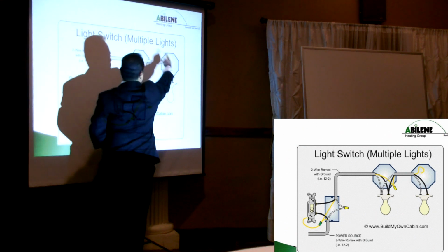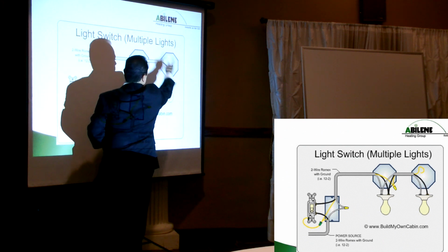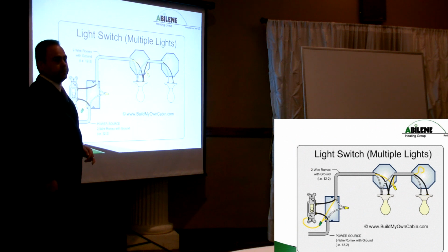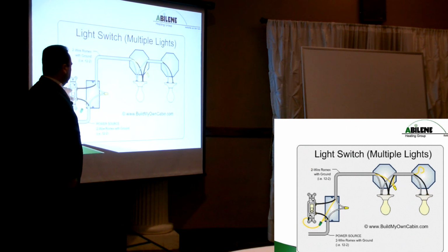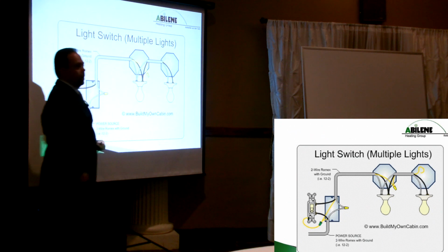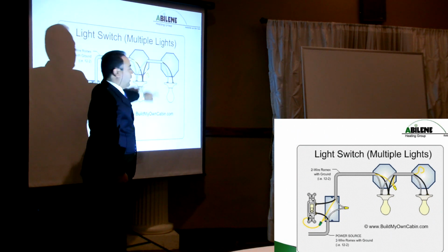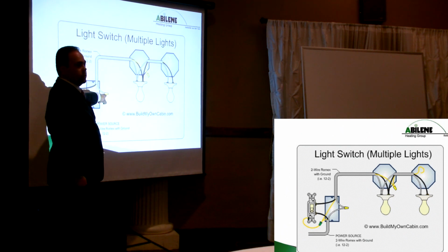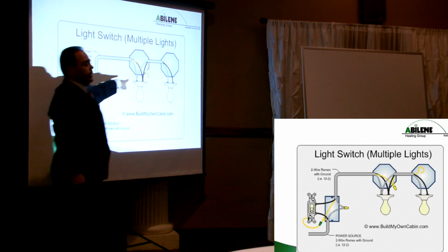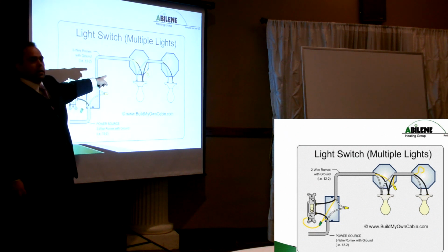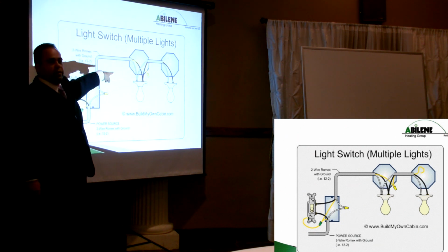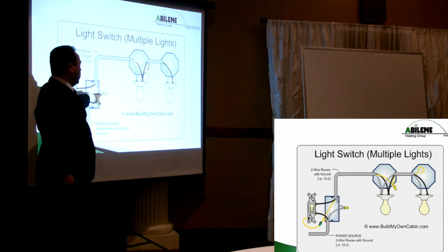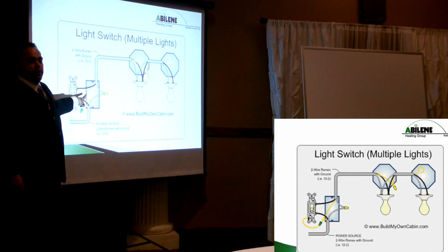This is a parallel circuit. All of it is in parallel with each other. Okay? Everybody get that? When the switch is open, current doesn't flow through that black wire. I need both the neutral and the hot in order to get 110 volts. If I open this, it's an open circuit, right? Will the light light? No, of course not. Just like Danny's theory, I'm not getting shocked. I don't have 110 volts there because this is open. Everybody get that?